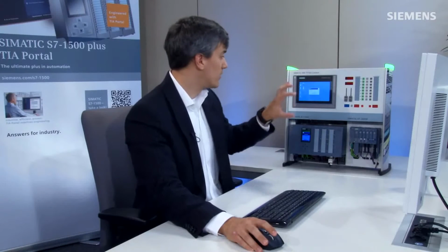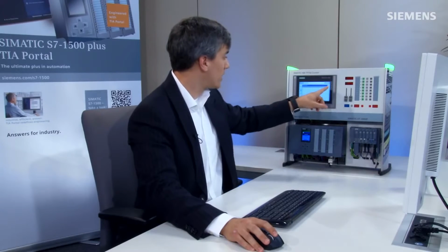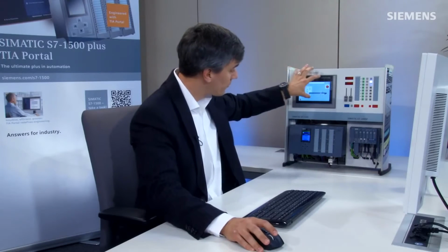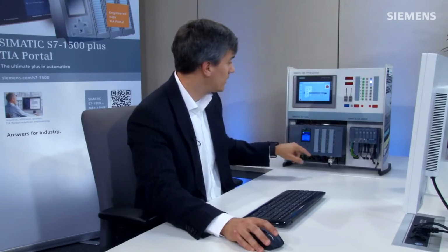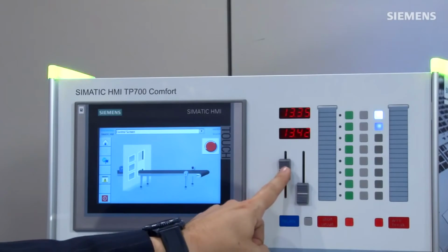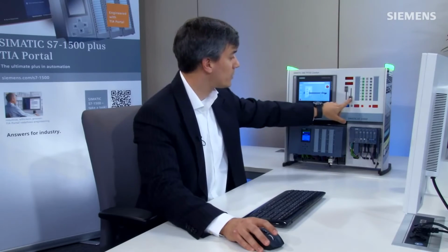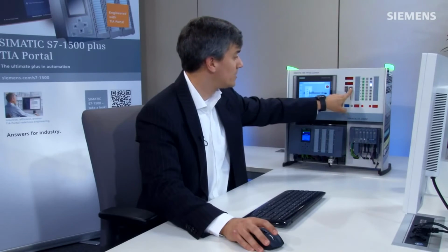So now it's actually going to go down and load the entire configuration of everything we've done, passing even the tags from the controller up to the HMI and the screens, and now we get a refresh and we have our completed system. At this point I can come over here and hit our easy button, and as you can see, control from the panel through the controller to the outputs is fully functional with this routine I've got running, and in fact my sliders of my analog inputs from here through the controller back up to the HMI are fully functional, even for these animations on the screen.